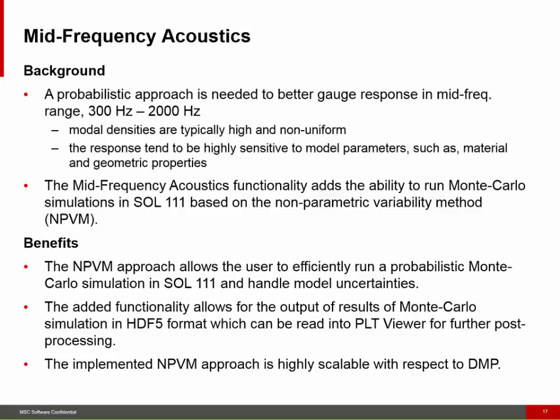That means that even a small perturbation in the model in terms of geometry, perhaps material or thickness, can result in significant changes to the response. That is why a probabilistic approach will provide more statistics to the results in terms of confidence interval and mean value, for example, in addition to just one deterministic result.